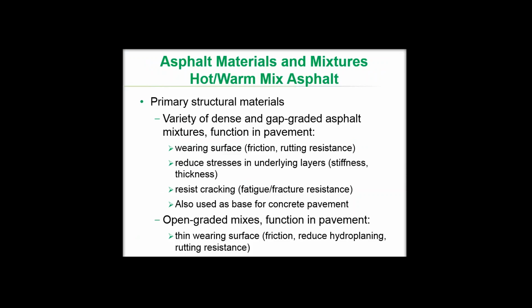Those asphalt layers also spread the stresses from the load and protect the unbound layers in the subgrade down below. So we're looking at the stiffness and thickness of those intermediate layers. For layers at the very top and at the very bottom, we're particularly interested in fatigue and fracture resistance under repeated traffic loadings. And asphalt mixtures are also used extensively as base materials for concrete pavement.